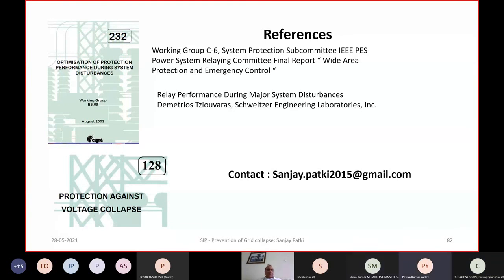Sir, just now you mentioned that we have to revise the stabilization resistance value according to the through fault increasing. Whenever a through fault occurs, there is no voltage developed in REF. How do we measure how much voltage is developing across the resistance? Because in a through fault, there should be no flow of current in the REF circuit.